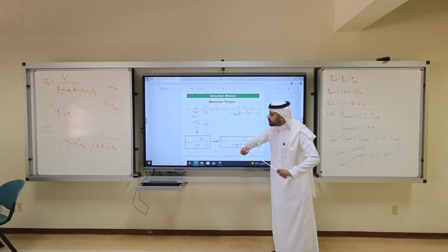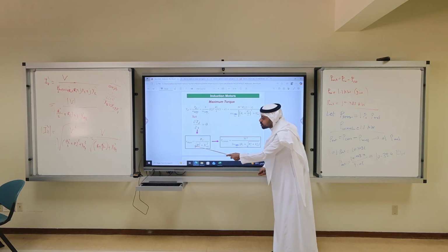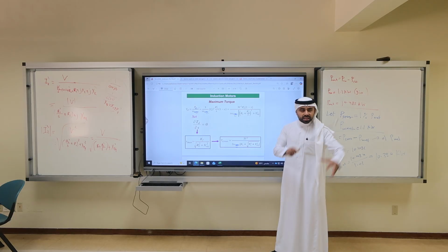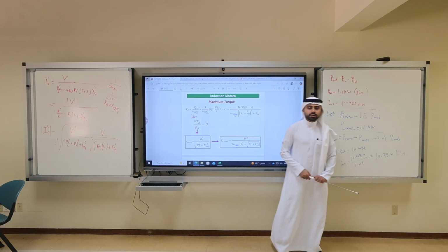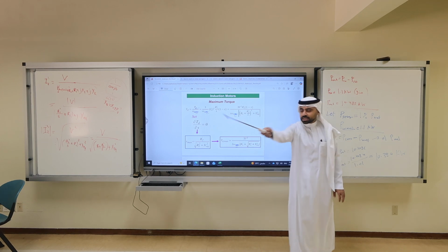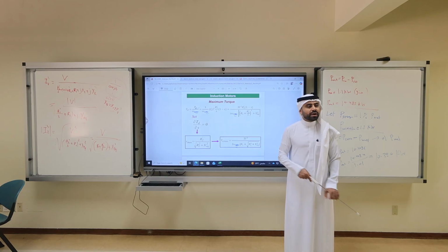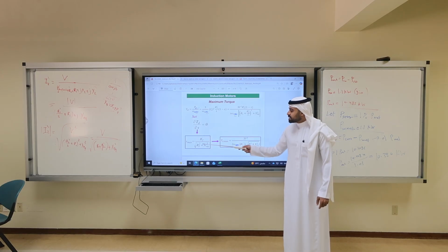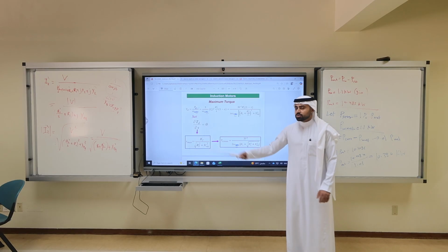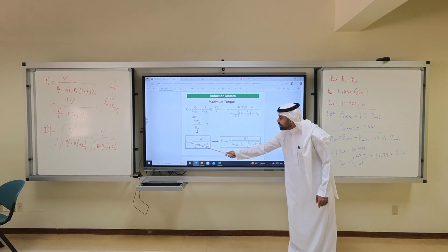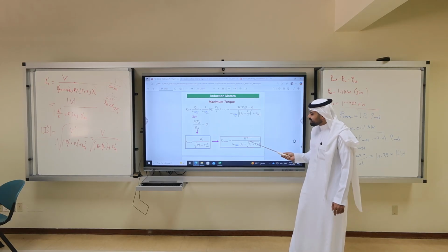It is this number, R2 prime over square root of R1 squared plus X equivalent squared. So if I change the resistance, basically the geometry of the machine, I change the slip. Now we see some machines have slip 2% from these equations, or 3% from this equation. Maybe if I'm going to be very aggressive in the exam, I will tell you R2 is that, X equivalent that. What is R1 to give you the slip of 3%? I have to make sure you know this formula or not. Clear as well? Plug this maximum slip here.